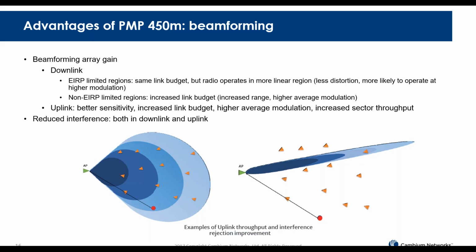In sector mode, this device is received at the access point at the same time where the access point is receiving the desired signal from the subscribers in the sector. So the presence of this interference will corrupt the reception at the access point and possibly force the subscribers to use a lower modulation level if the interferer is always present.